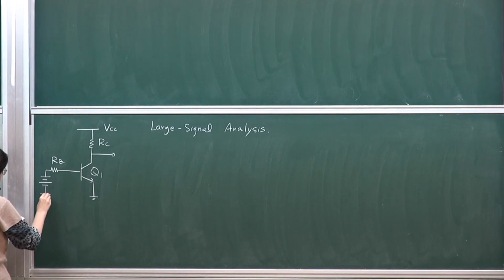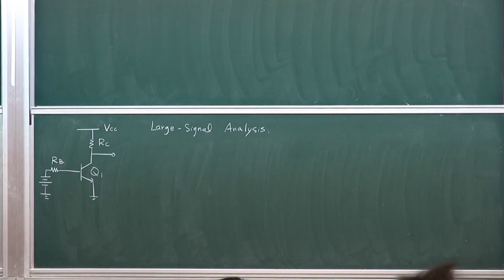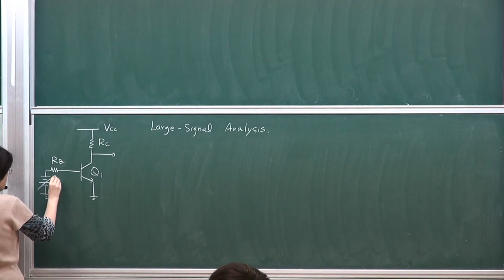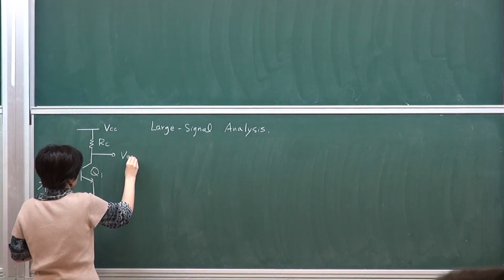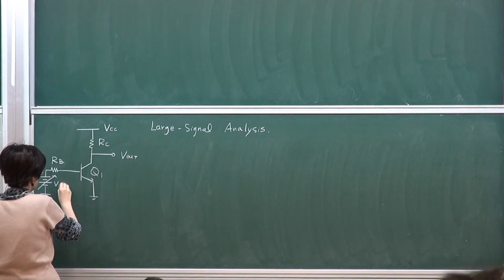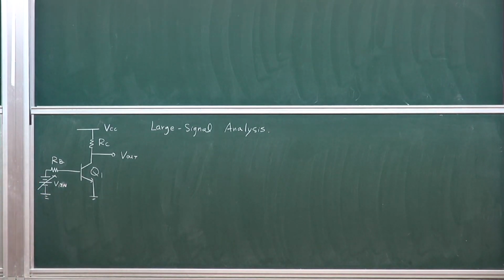So what is actually being done, if you actually have the circuit, what can be done is that you simply sweep your input and then look at the output, the DC level. I want to see the whole transfer characteristic.